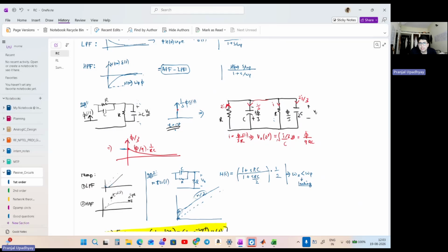And now the currents will start to flow in the circuit. So if this current is I, since this is R, this current will be 2I, right? And how did I say that this current is I and this is 2I? I said it very simply because the voltage across this resistance at that instant is 5 by 3, which is I, which is 5 by 3. And that's why this I current will flow. And the voltage across this resistor because of this capacitor is in the opposite direction. It's twice. So that's why I'm saying that 2I current will flow.